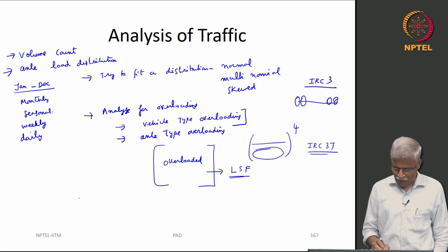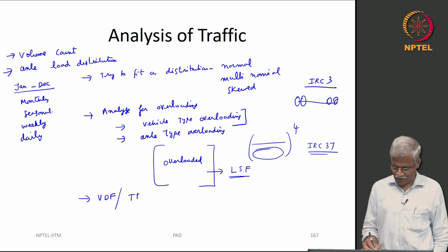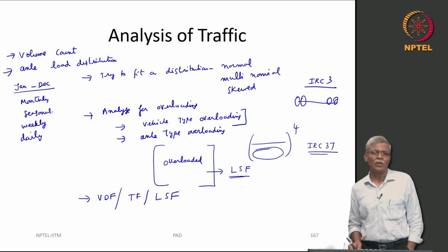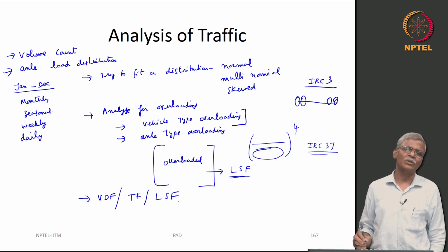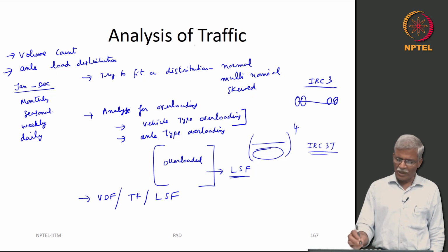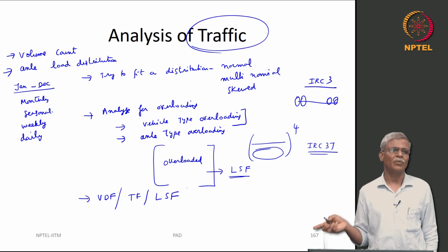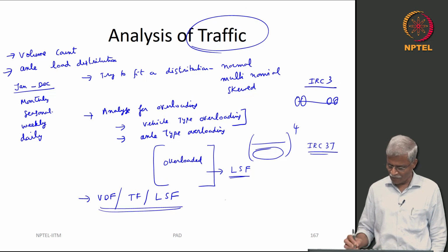Now, continuing on whatever I said, you need to also use this opportunity to explore this concept of vehicle damage factor, truck factor, load spectra factor. They may not necessarily give you the same ESAL value. They will give you slightly different values and in some cases completely different values also. That is why we are now talking about traffic, because this is the most important input that you are giving to your pavement design. So, you need to understand this and do this carefully.